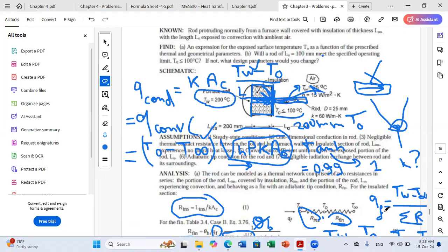So this is a design problem that can help us understand the different parameter effects on our T0. Our purpose is to get T0 as minimum as possible. So we can work on two aspects: better insulation here, and better convection from the fin in the other part. That's why we can optimize the conductivity of the material, the length of the fin, etc. Any question on this?